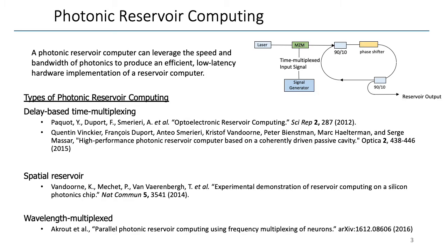The simple structure of a reservoir computer, with its untrained internal connections, has allowed for its implementation in various analog physical systems. In particular, its implementation in an optical or photonic system is very enticing, because photonics has several advantages over electronic processors, including the ability to simultaneously process several terahertz of bandwidth on a single physical node, very low propagation losses of high bandwidth signals, and the ability to perform parallel processing via wavelength multiplexing.